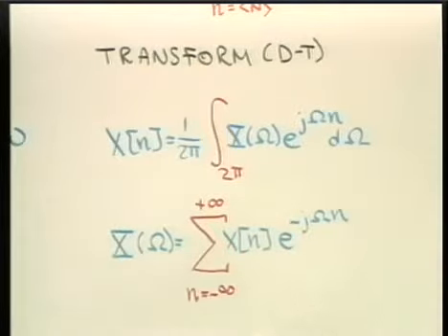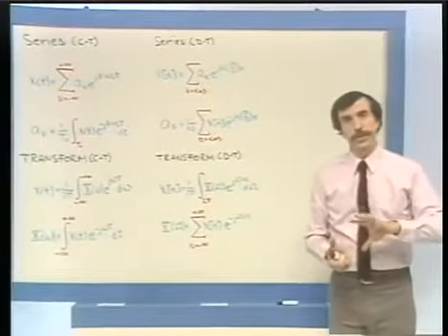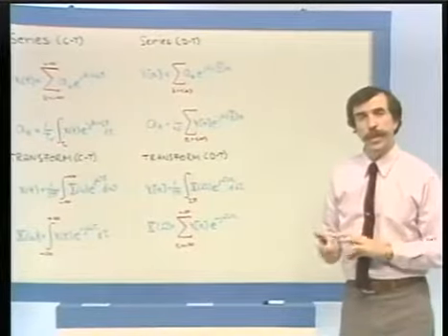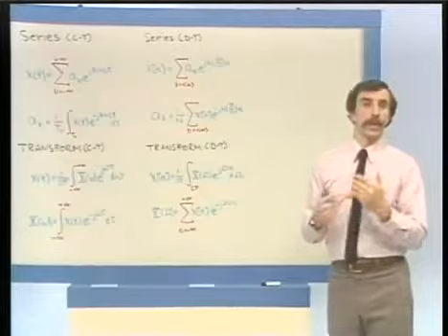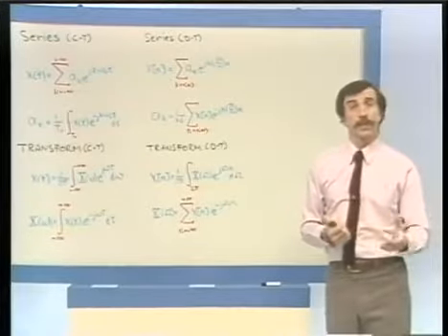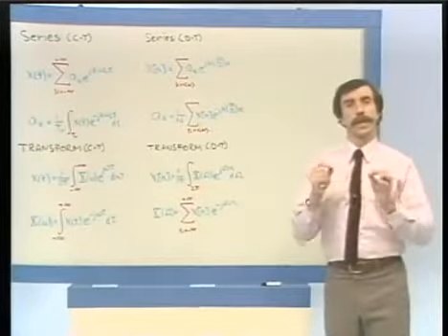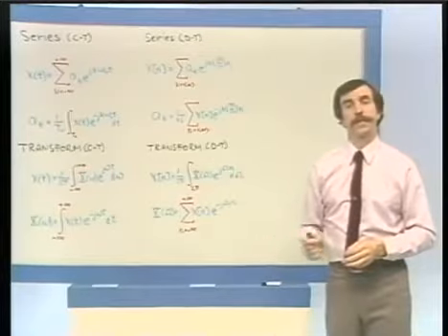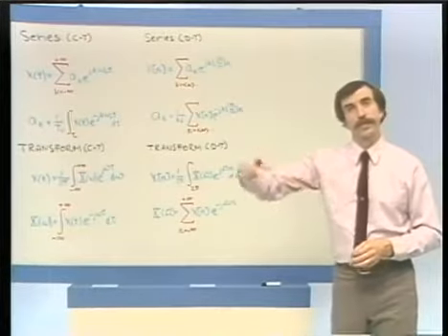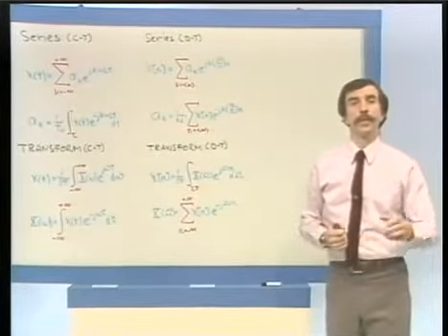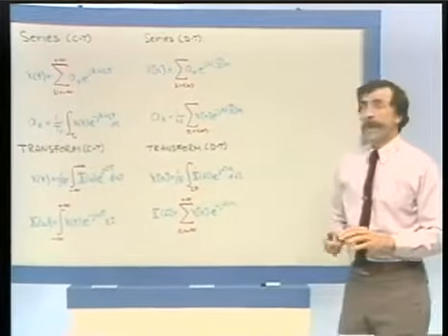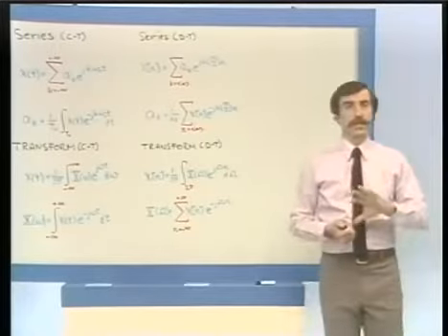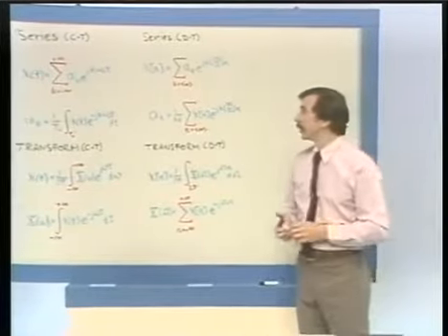And so the important difference between the continuous time and discrete time case arose in part out of the fact that discrete time is discrete time, continuous time is continuous time, and the fact that complex exponentials are periodic in discrete time. The harmonically related ones periodically repeat, whereas they don't in continuous time. Now, this, among other things, has an important consequence for duality.